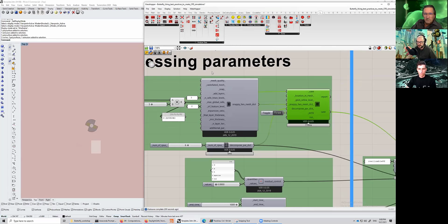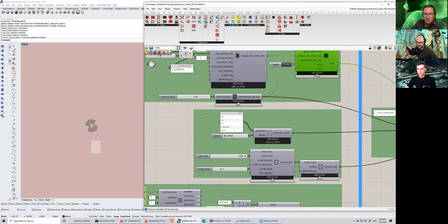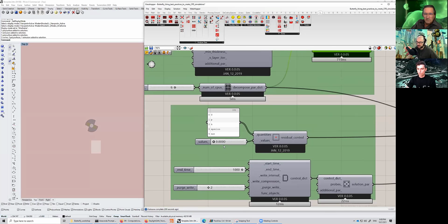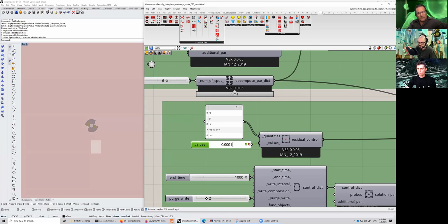The other inputs I said, the solution parameters, I won't go very deeply into it. This is the physics of CFD, right? Here we just tell it when to stop going. So every time CFD runs an iteration, it has some residuals, the error, imagine, of the calculations, right? So here I've told it to keep going until you reach 10 to the -5 of residuals. It's a very standard best practice thing that people do. Some people might do much more, depending on the case, right? But for outdoors, I think this is very good. You might never reach it, if I'm honest, with this sort of